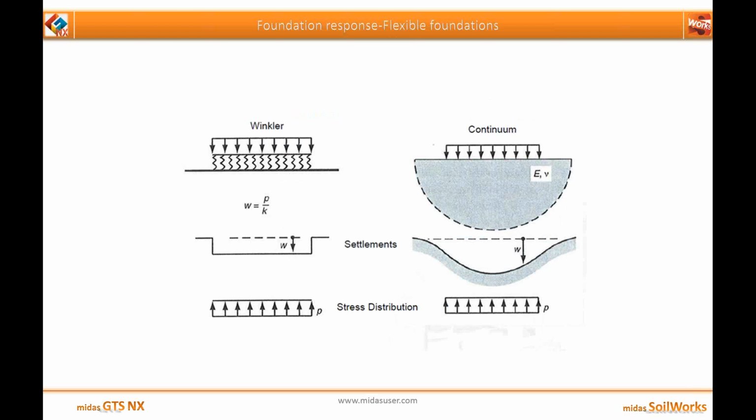Now next is the foundation response for flexible foundation. In this, the stress distribution variation is very much similar to what we expect in the structural behavior. But once again, the settlement variation is not very uniform, and it is very much different from what we obtain in the continuum model and structural model.